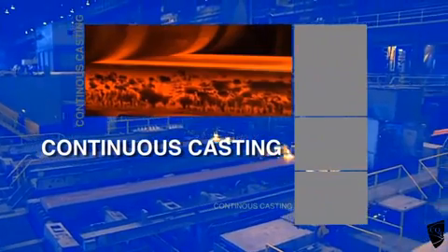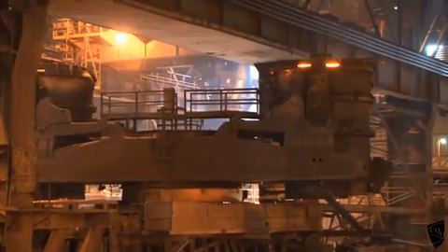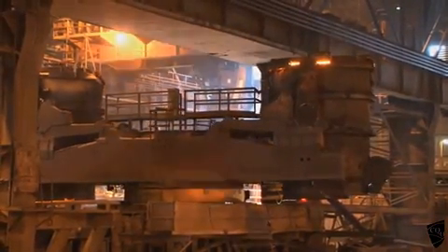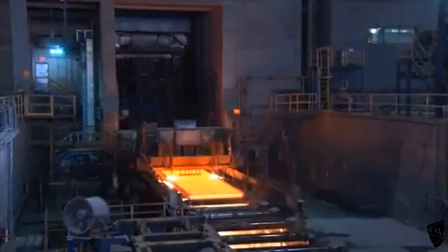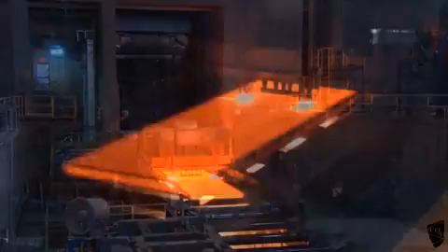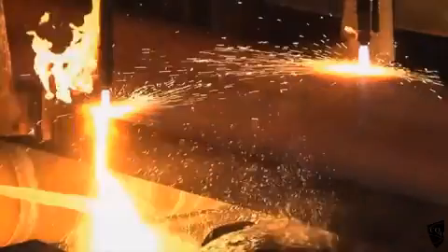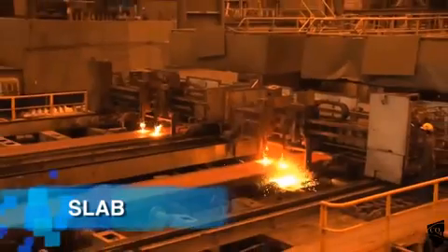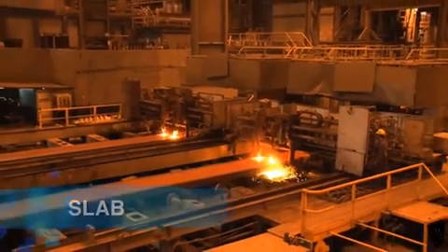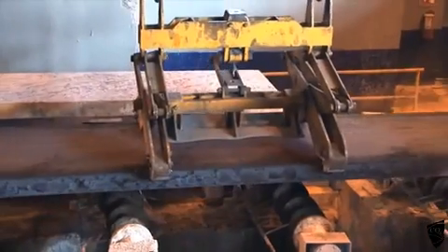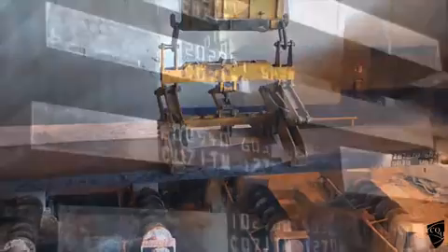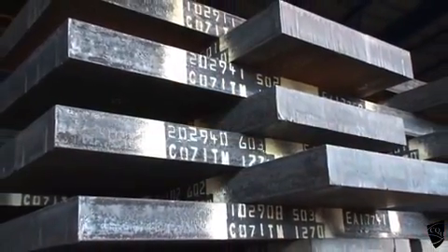With the treatment completed, liquid steel is transformed into slab on equipment called continuous casting machines. In this process, as it passes through a series of rollers with a cooling system, it begins to solidify until it becomes a slab which is cut with oxygas to the required dimensions. The steel slabs are produced in different thicknesses, widths, lengths, and weights, and each piece is labeled for later processing by hot rolling.